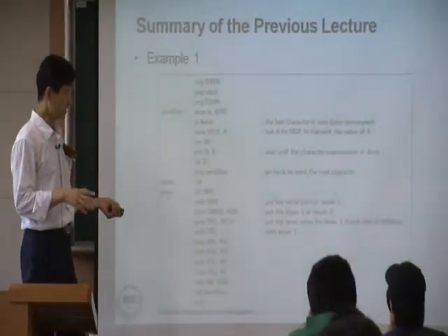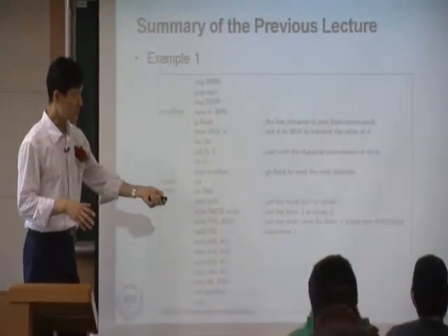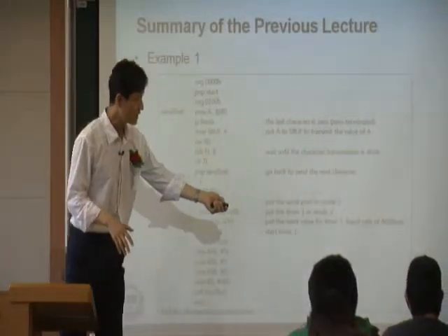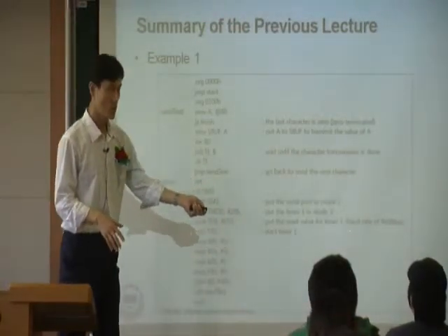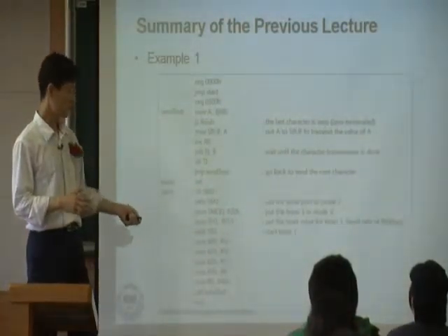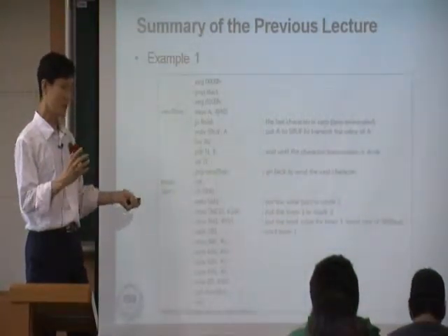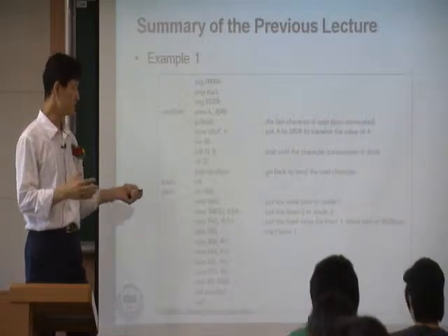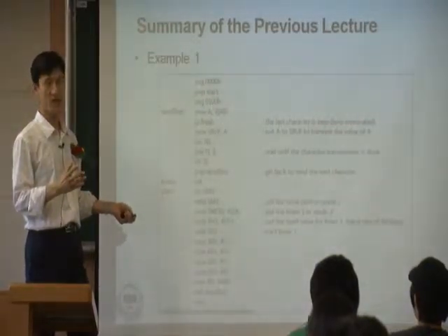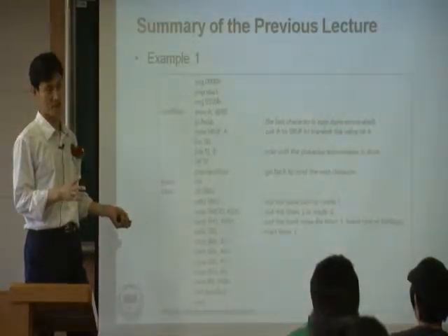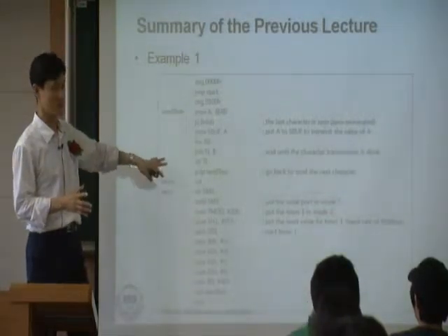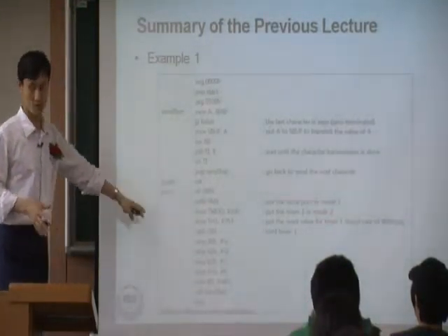In addition to that, in order to set a certain BPS, in order to make it 9600 BPS, we are using timer. See here, we are using timer hardware. We are also using serial communication hardware, but we are not using interrupt. We don't need any interrupt right here.